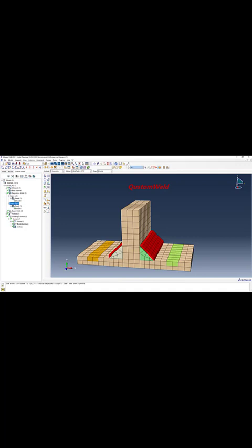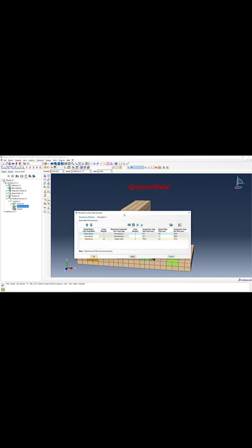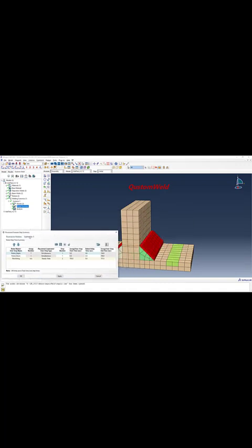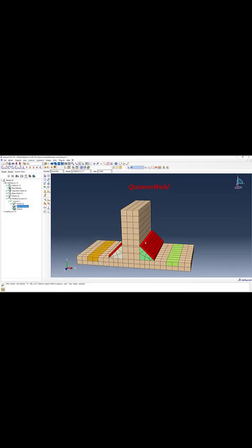And then if we look, let's see here. Oh, I'm sorry, we're looking at the wrong one here. Let me go to this one. So if we look at this robot summary, this is defining a welding scenario, and we've got all the steps defined, and what we've done is we've just hit this button here to add an extra step to define the machine region. So that's all that's really done in this analysis. So the analysis runs and removes that material at the end.